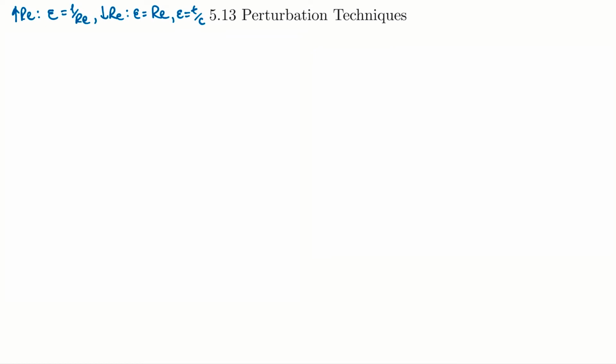Then the boundary layers would be treated differently than the other regions by taking the lateral coordinate y and looking at it in terms of the boundary layer thickness delta, and then defining this eta parameter that is y over delta. And the objective is to rescale the variables so that they're all finite in this thin singular region. I'm going to go through a description here, and following this, we're going to look at an example of a regular perturbation problem so you can see this in action, and I think that'll help us understand it a little more, because it's a pretty unique way to solve these problems.